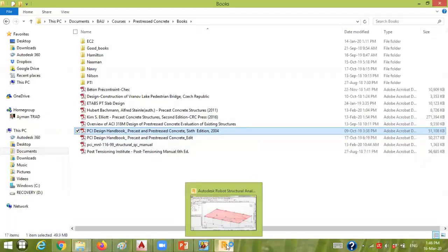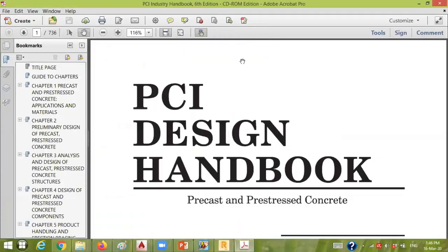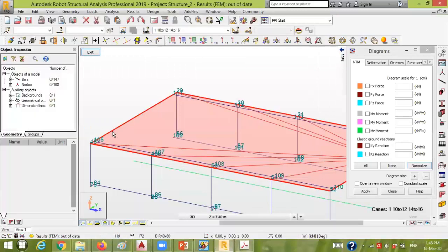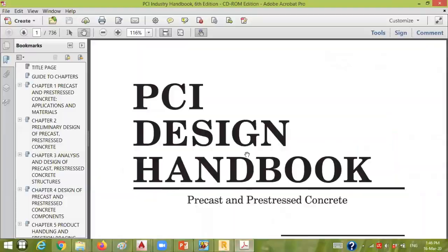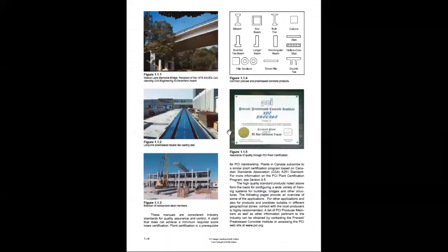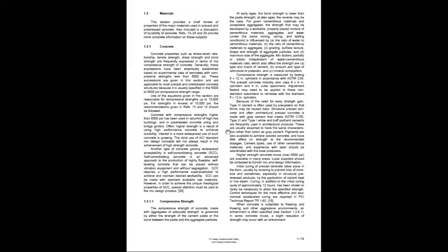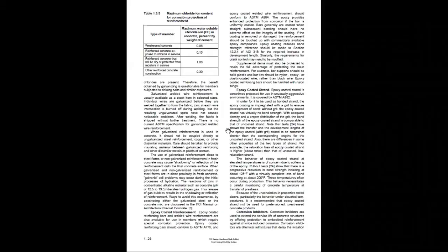Now my span is around 12 meters. The span of the beam here is around 12 meters. So considering the beam is simply supported, 12 meters over 16, as calculated previously, is 750 millimeters. Over 25 is 30 inch. We'll try just to figure out what is the geometry of the double T beam having a total depth of 30 inch.